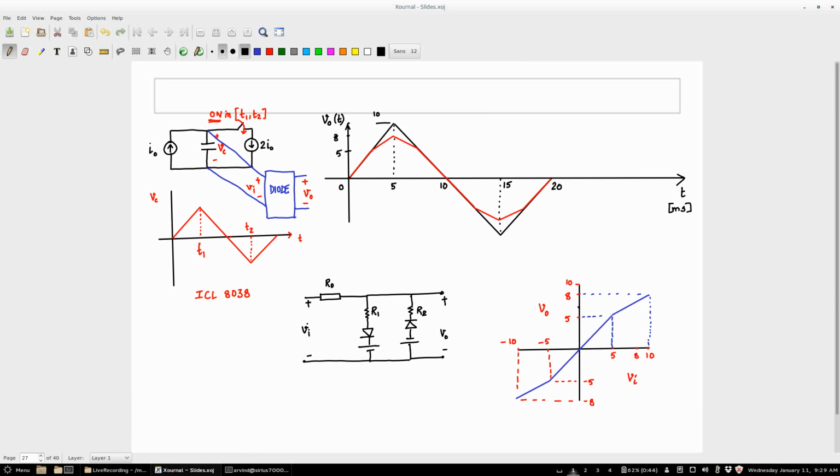Now if R naught is not required, say both diodes are off, V naught is equal to Vi. Then you turn one on. What will happen to V naught and Vi if this R naught were not there? It will still be equal, right? So that means R naught should be there, right? So think about how you will design this.